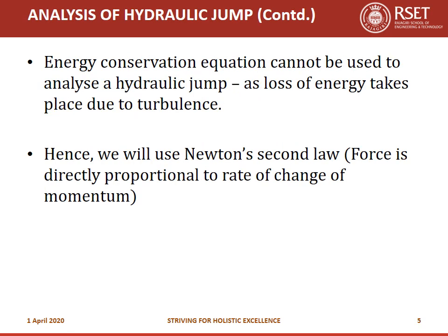While we are analyzing the hydraulic jump, we cannot use the energy conservation equation. The energy conservation equation can be of many types. You can use the Bernoulli equation, where you consider all the forces and energies, pressure energy, weight, etc. However, the energy conservation equation cannot be used to analyze a hydraulic jump, basically because energy is not conserved in a hydraulic jump. There is a loss of energy taking place due to the turbulence happening in the hydraulic jump.